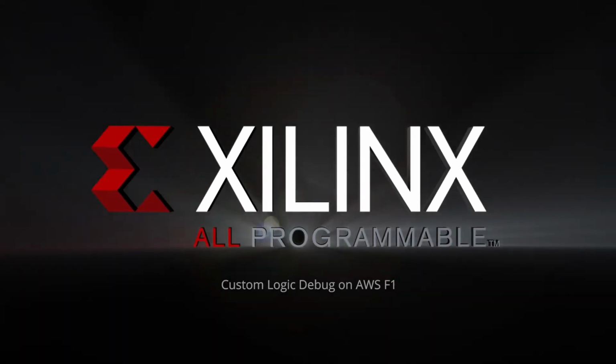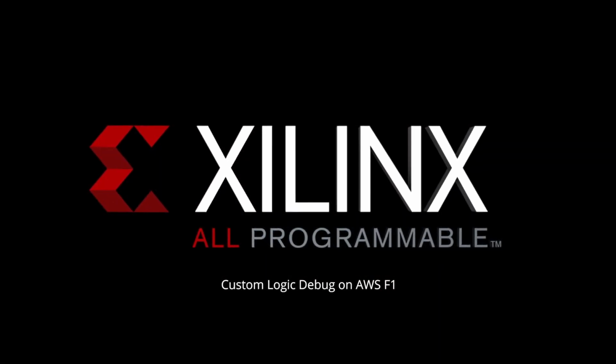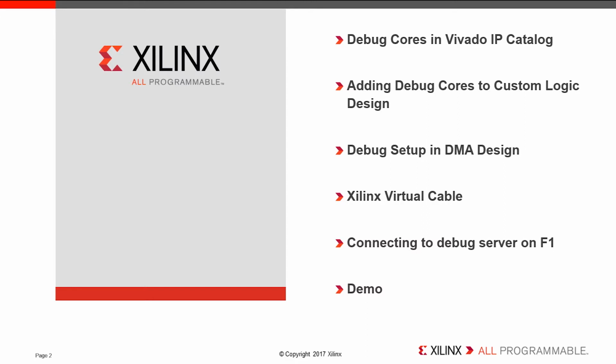Hello and welcome to this video on how to debug your custom logic design on Amazon F1 instances using the Xilinx UltraScale Plus FPGAs. In this presentation, I'll walk you through the various debug cores that are available as part of the Xilinx Vivado IP catalog. I will also go through the steps required to customize and instantiate these debug cores into your custom logic design.